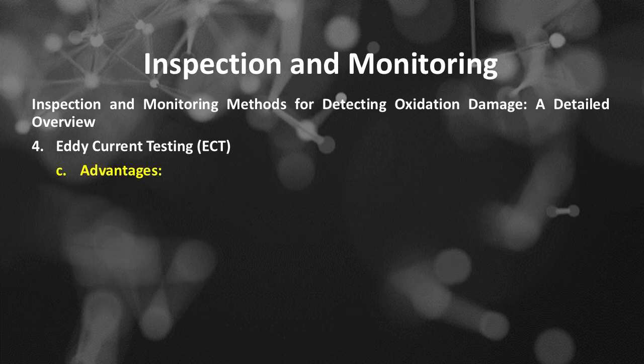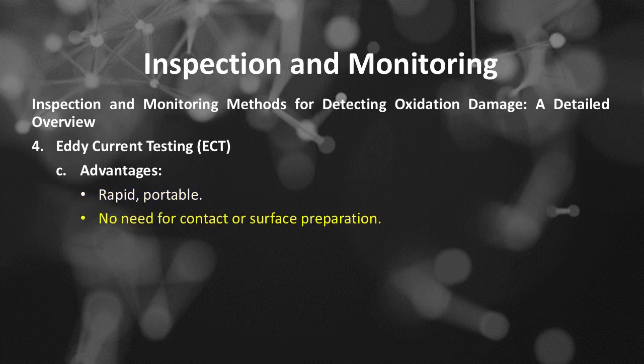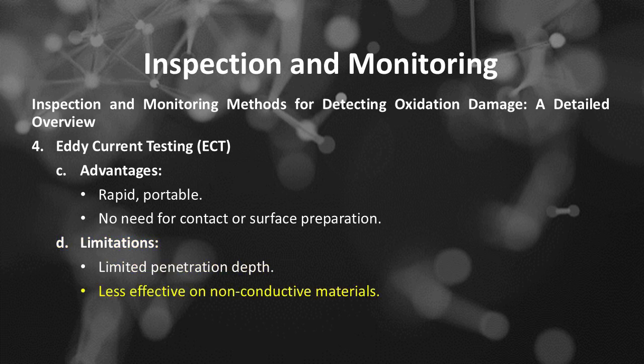Eddy current testing advantages include being rapid and portable, with no need for contact or surface preparation. Eddy current testing limitations include limited penetration depth and being less effective on non-conductive materials.